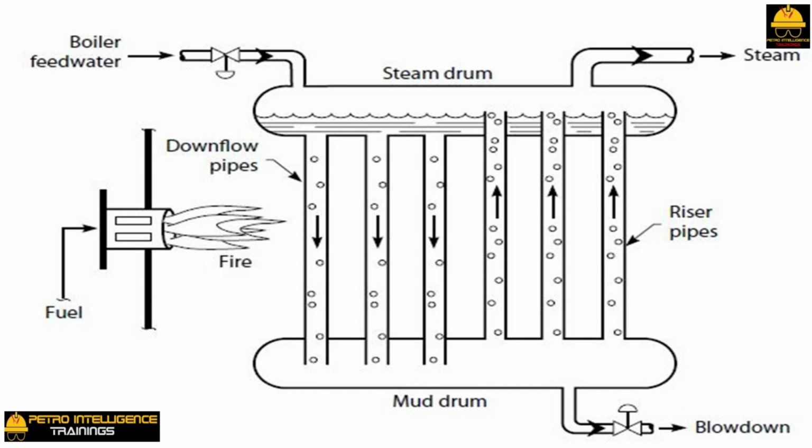It is really the quality of the treated boiler feedwater that sets the blowdown rate. Deionized or demineralized water might require a 1 to 2% blowdown rate. Hot lime softened water might require a 10 to 20% blowdown rate. The amount of hardness deposits and silicates in steam is a function of entrainment of water, as well as the TDS of the boiler feedwater. A well-designed boiler, then, often is equipped with a mesh-type demister pad to remove entrainment from the produced steam.